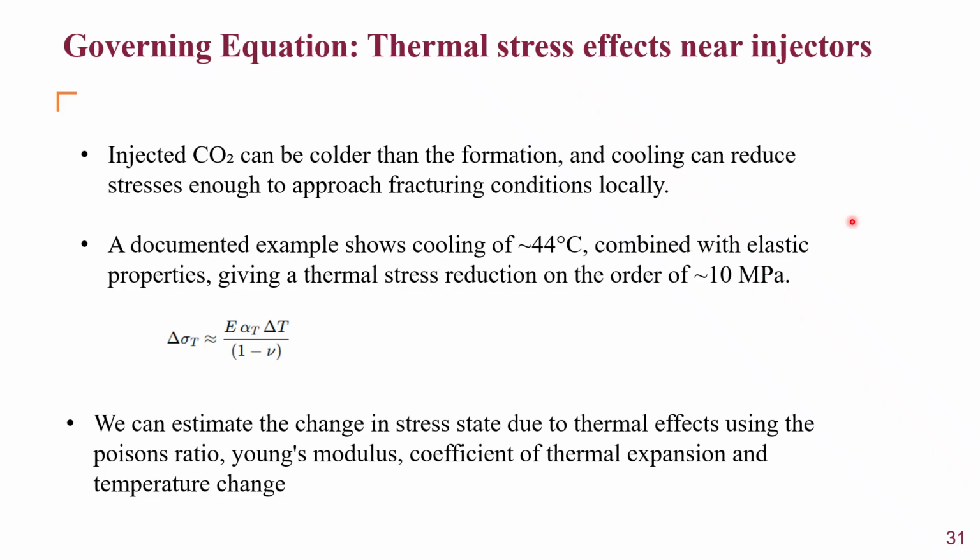And because the CO2 injected is normally colder than the formation, the cooling can induce stresses and can also cause some fracture conditions locally near the wellbore. Now, the thermal stress is given by E, that's the Young's modulus, times the thermal expansion coefficient times the change in temperature, all divided by 1 minus Poisson's ratio. That's the change in the thermal stress.